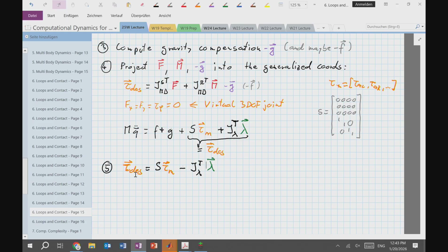But I can, in a sense, right, if I think about these forces, left foot, right foot, they have a vertical component and a horizontal component. And rather than doing this on one foot and nothing here, I could do this on one foot and that here. And since forces can be moved along their line of action, the effect is going to be exactly the same, right? So that gives me sort of this extra degree of freedom.